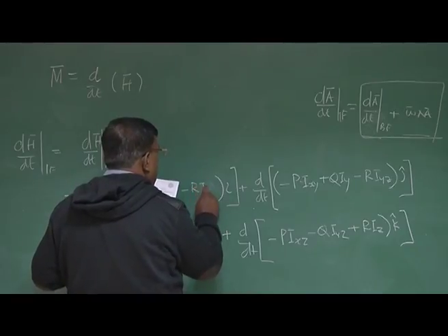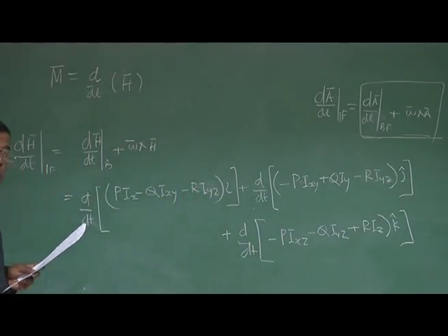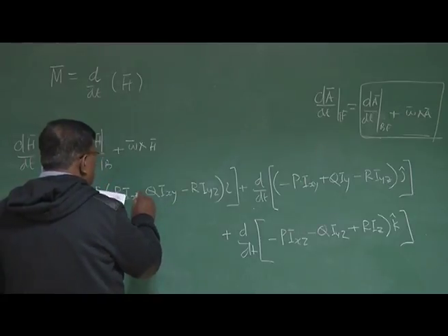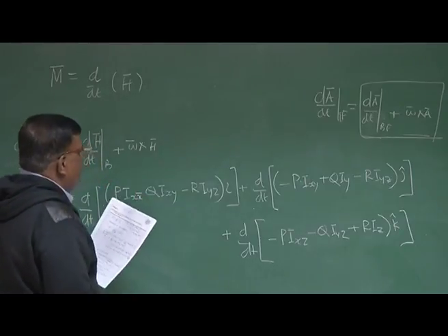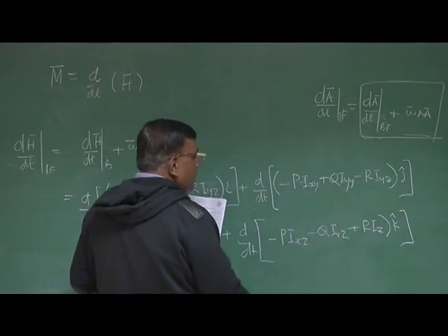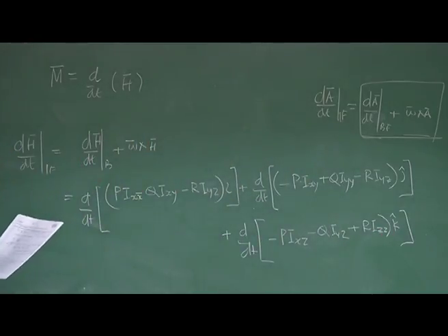So many expressions you have to write, so be careful. That's why I repeat, once in a lifetime you should develop this. Do this by your hand, and life will be very comfortable. You cannot avoid this if you really want to be a good flight dynamics person. Generally, notation-wise, we would use double subscripts. For Ix we write Ixx, for Iy we write Iyy, for Iz we write Izz, right? So the third is minus p Ixz minus q Iyz plus r Izz. Fantastic.